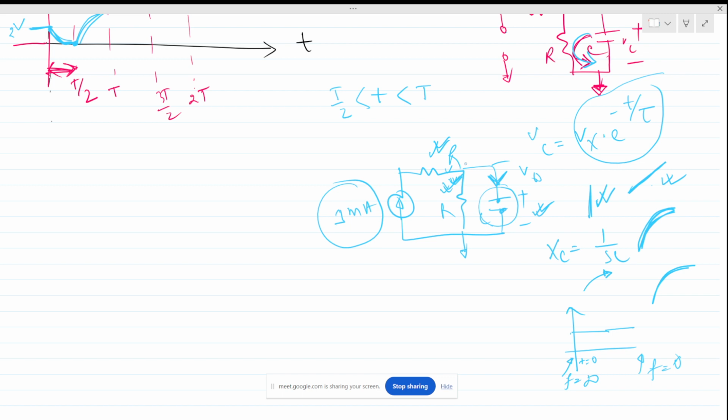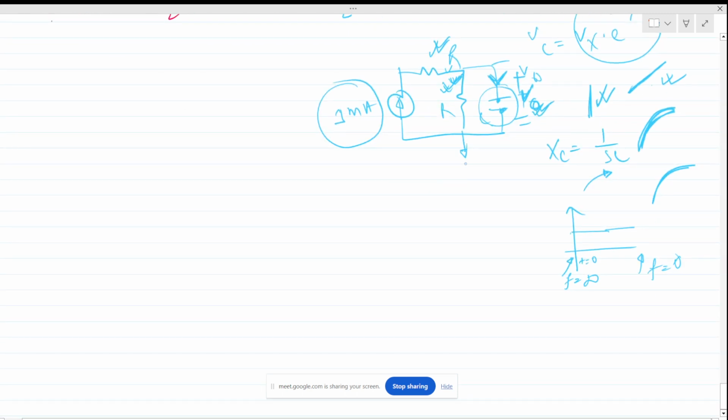So what will be the voltage at this node? The maximum potential can be this V out maximum. V out maximum will be when this impedance is infinite, right? So the maximum will be nothing but I into R, the voltage drop across this resistance.